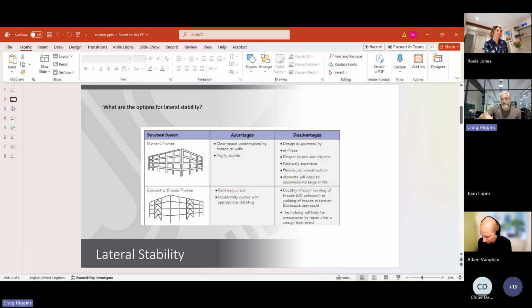And if you can allow bracing, so bracing is essentially allowing members to stretch, and steel is a material which can resist tension better than anything else. So with diagonal bracing, if you're always thinking about where can we position bracing, you will end up with a more efficient structure, you will end up with less embodied carbon.